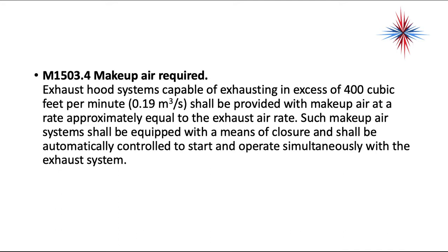Makeup air is required for any exhaust hood that is capable of exhausting in excess of 400 cubic feet per minute. Okay, makeup air is basically you're bringing in fresh air to replace the air you are removing. The makeup air has to be at a rate approximately equal to the exhaust air. In other words, if you are exhausting 400 cubic feet per minute, you have to bring in 400 cubic feet per minute. Such makeup air systems shall be equipped with a means of closure and shall be automatically controlled to start and operate simultaneously with the exhaust system.